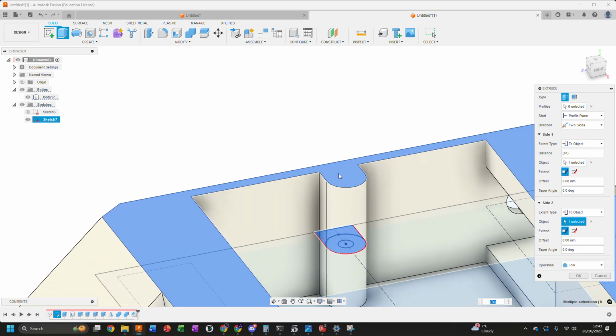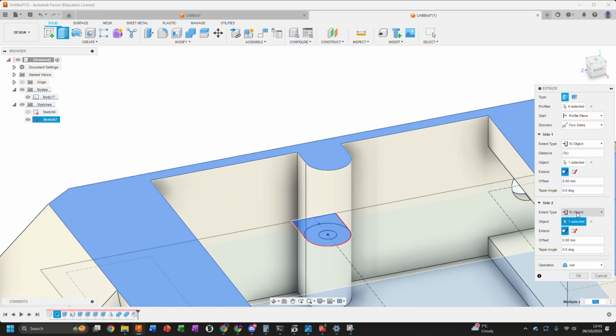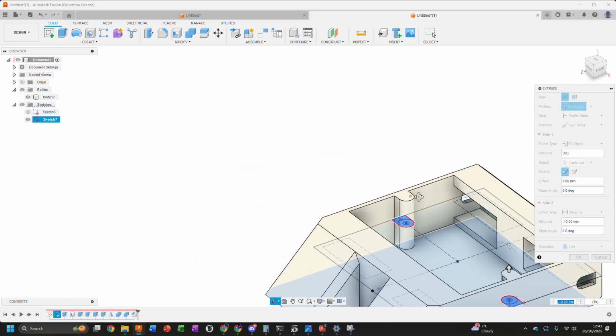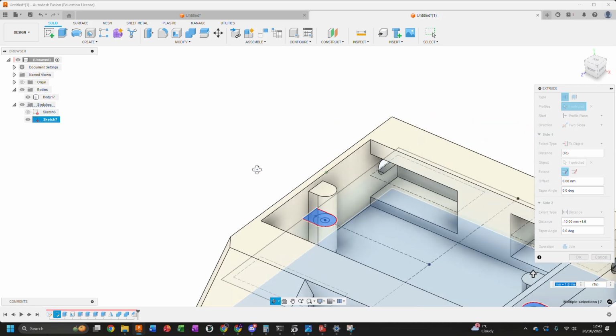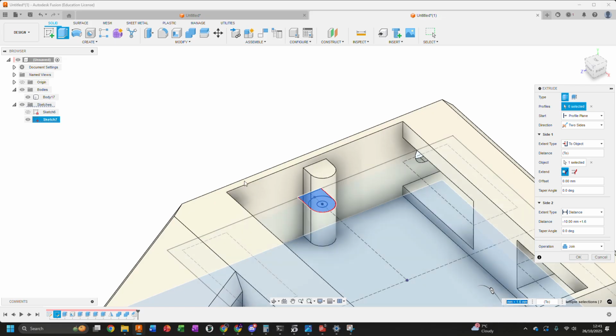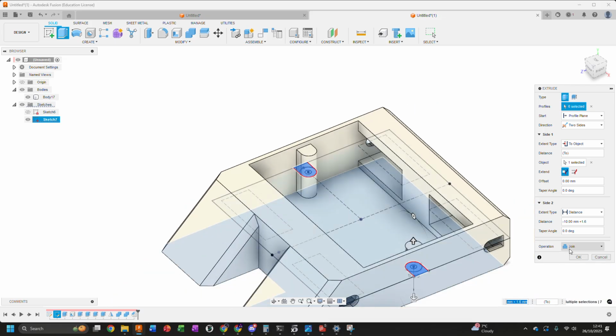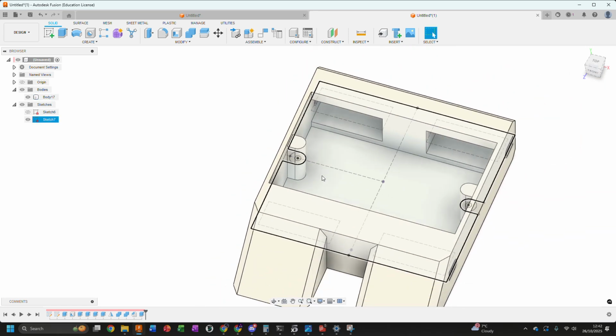So in order to have this be recessed from the top surface, what we can do is now select distance here, and we can see it's minus 10 millimeters, right? So what we can do is add plus 1.6. Say we want our lid to be 1.6 millimeters thick. You can recess this from the top surface by 1.6 millimeters so that our lid is flush with the surface. Okay, brilliant. And now we need a through hole through which the bolt can go through to secure the lid.